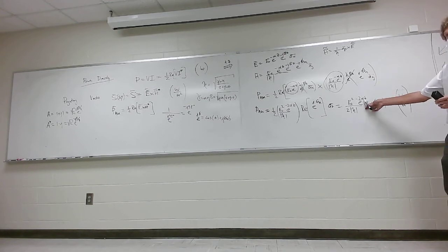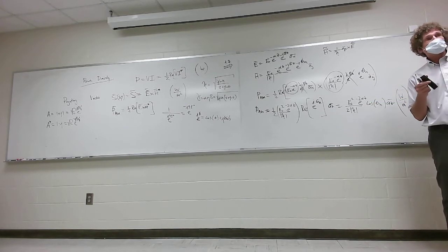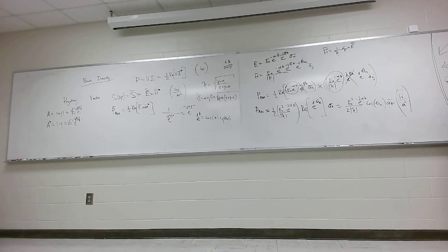Obviously, this is something that decays with z, right? If alpha is non-zero, then as you go, the power that's actually flowing decays. What's happening is the power is lost in heating the environment, because of the conductivity of the region, it would thermally heat it. Do you all see that, class? And it's going down twice as fast as the E field goes down, you might say, correct? Because it's going down as e to the minus 2 alpha z.